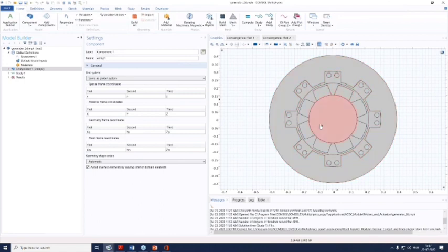Now here in this case, the way geometry has been created is, first of all, we create the stator part. We remove this using the difference operation, and we create one hole over here. Once the hole is created, you need to create a union for the outer object, then create the inner object, create a union between the rotor objects, and then apply the assembly. Hence in such cases, the sequence will definitely matter: at which stage you are creating the rotor parts, at which stage you are creating the stator parts, and how these objects are interacting with each other.